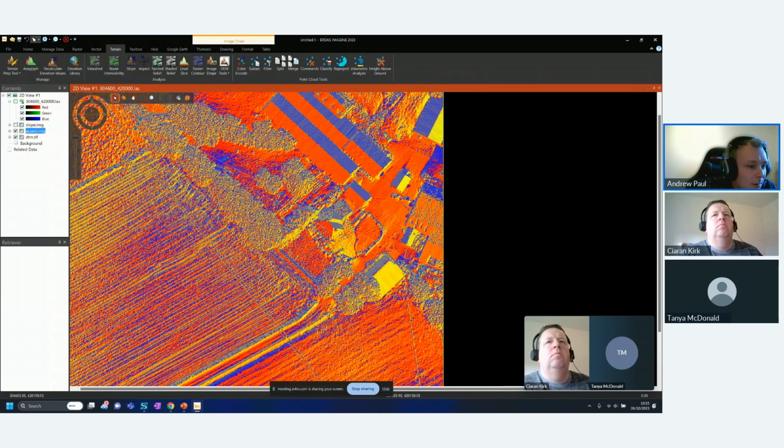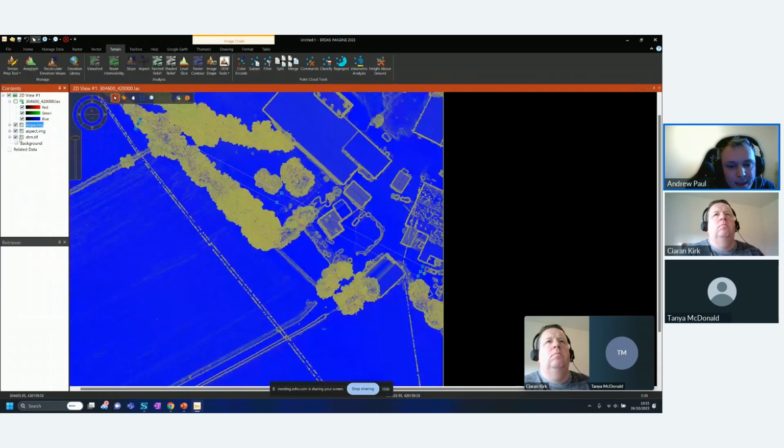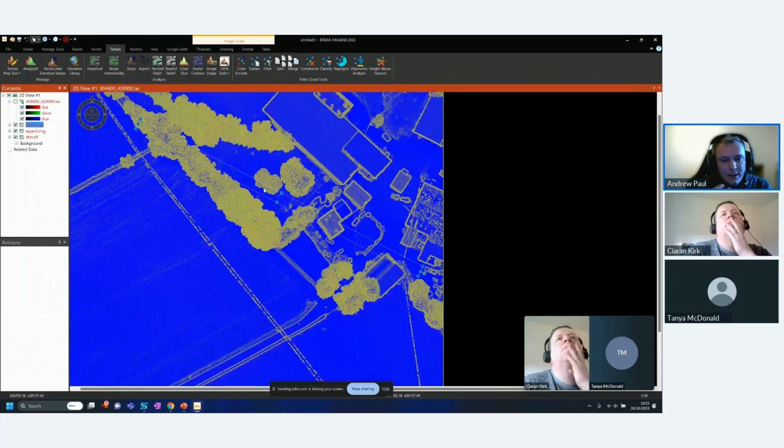And we can also calculate slope. We can look for areas where there's going to be a much larger variation in slope, or where it's going to be a bit more flat. And again, you can incorporate that data along with the aspect data, and export all of that into the viewshed, into your analysis, and you can then incorporate that with vector data to show which buildings would have the best solar potential.